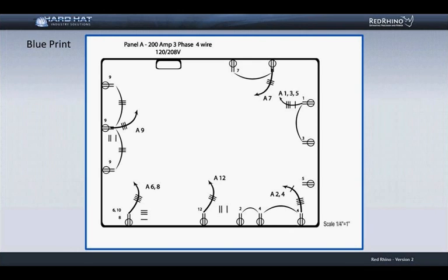Another thing is this. I always use a highlighter and mark the conduit runs on the blueprints after I roll them off. Lastly, usually there are junction boxes needed in conduit runs, and junction boxes are oftentimes not shown on the drawings. When I know that a junction box should be included and it's not shown on the blueprint, I draw a picture of the junction box, just a little square on the blueprints, and I include the junction box on my material takeoff form.